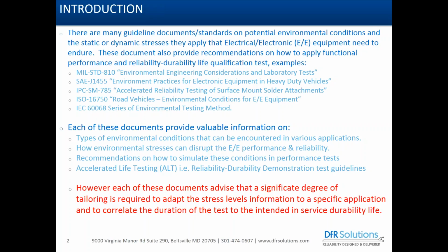So some of these standards that are very popular for many are like MIL Standard 810, environmental engineering considerations and laboratory tests as they apply to military and defense equipment. Then SAE J Standard 1455, environmental practices for electronic equipment in heavy-duty vehicles. IPC SM 785 defines accelerated reliability testing methods for surface mount soldered components.